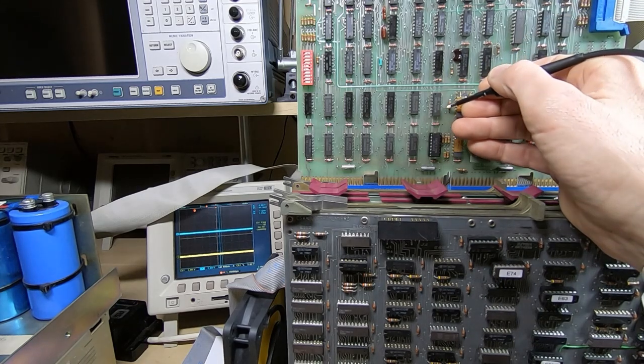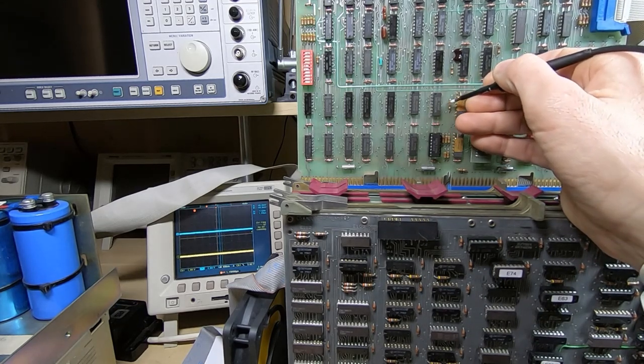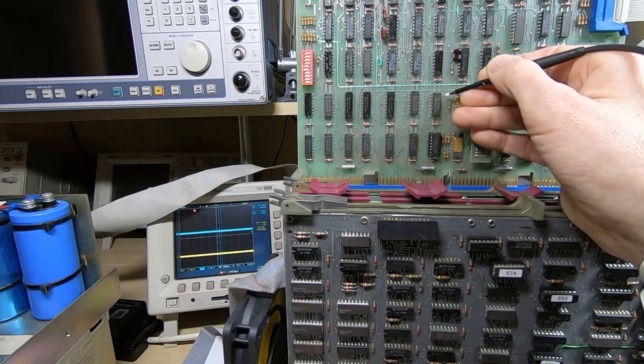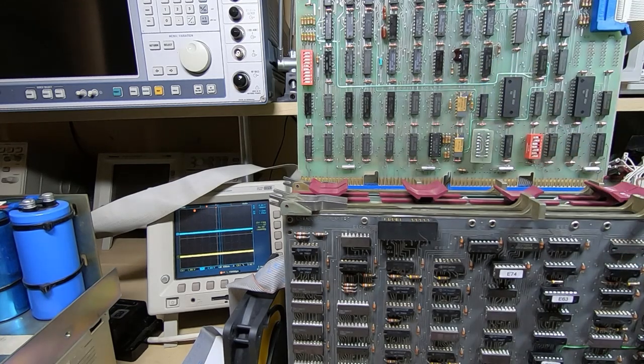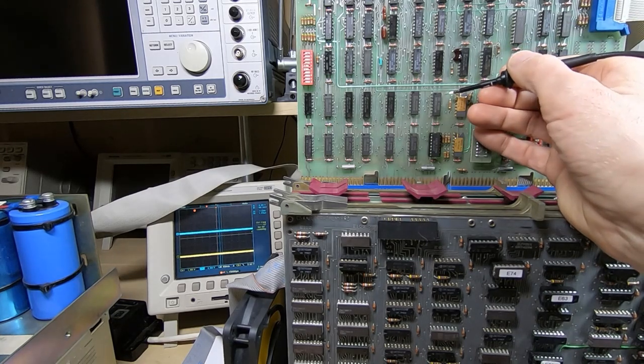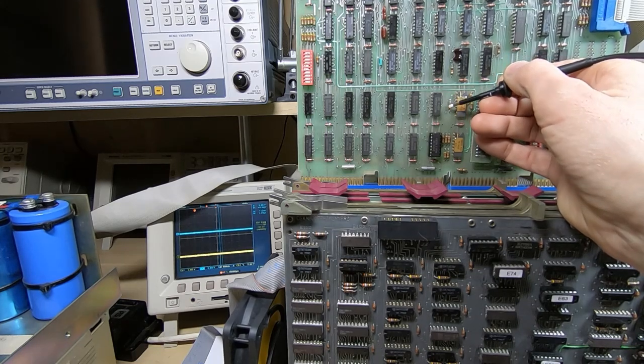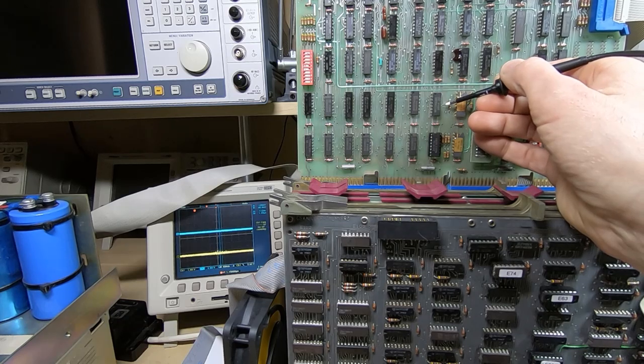So pins 10, 12 and 15 should all be low, which they are, so that's working so far. And what I can do now is send a function command that should set the bits. So I'll send a value of 3, that will set the first bit to a 1. I've sent a value of 3, and we should now find that the first bit has changed to a 1, and it has, you can see on the scope there, yellow trace. The other 2 bits should still be 0, which they are.